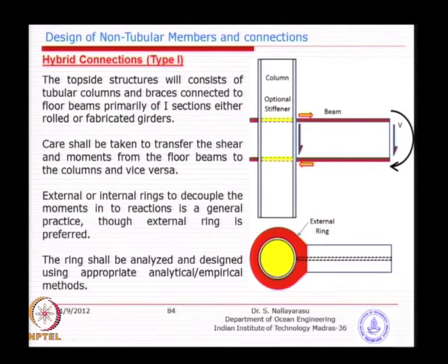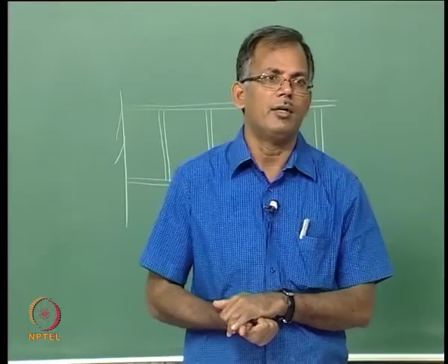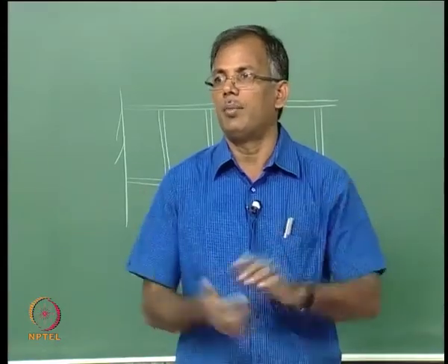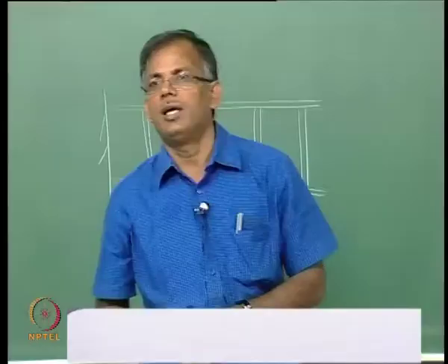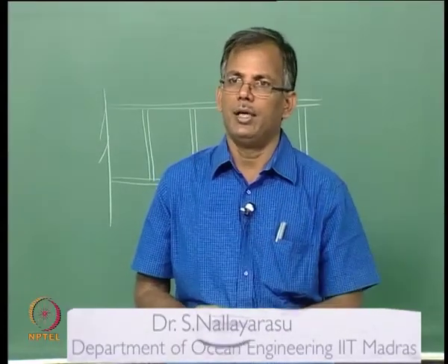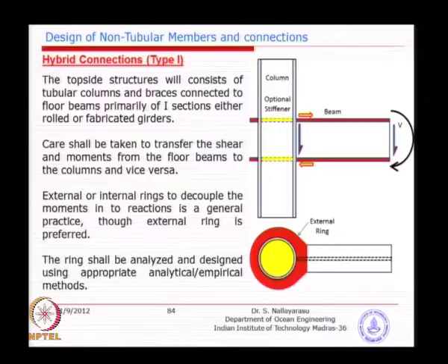If you look at some of the textbooks, you will be able to find curved beams in nature. I think you might also have studied curved beams in your applied mechanics. So, you can just take the load and apply it, very similar to an arch, only here it is a double arch closed section. So, you can design the ring, and then allowable stresses can be taken as 60% or 70%, and then this ring needs to transfer the forces by means of a circumferential shear along the pipe section.